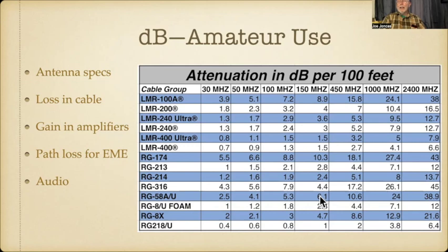If you were putting out 100 watts, which is not likely on that frequency, you would be cut first at 3 dB down to 50 watts, and 3 more dB would be down to 25 watts. So if you had a typical 30 watt transmitter, you would be cut down to 15, and then down to 7.5 watts, which is hardly more than a handheld.